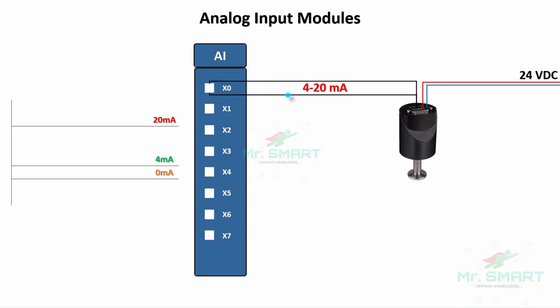To understand this, let us consider a scenario where my pressure sensor is going to measure the pressure range of 0 to 10 bar. During initialization, this 0 to 10 bar range is scaled between 4 to 20 milliamperes. This makes the sensor produce a minor current of about 4 milliamperes, even when it is not sensing any pressure and the pressure value is 0. What happens if the sensor is faulty or there is a failure in input supply to the sensor?